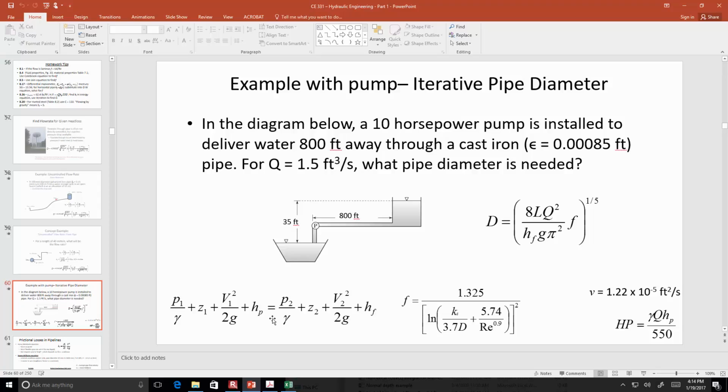What is it? It's the other way, actually. If you make the pipe bigger, then the flow rate is going to be bigger than 1.5 cubic feet per second, because a bigger pipe diameter means that there's going to be less resistance. And so actually the system will pump faster than it can if the pipe is smaller.